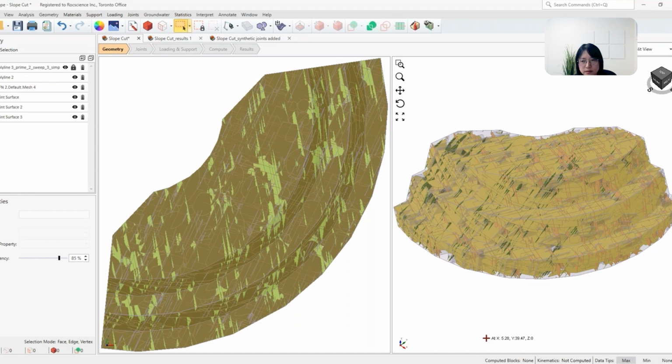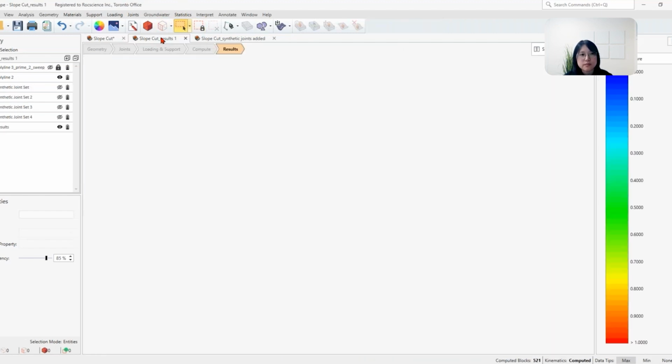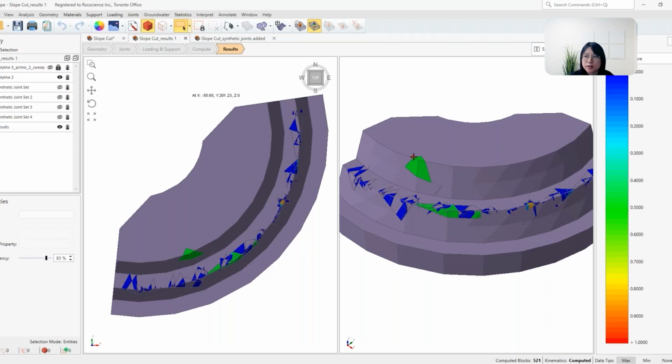Does this require us to define anchors pull-out resistance? Oh, I see. Okay. So for instance, if I have a model here, RocSlope can provide you with the failure depth, and then the failure depth you would then use to design for the anchor length itself, right?